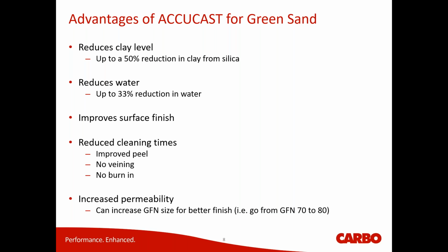So that's just one thing to consider when you're looking at this: you want to really be looking at your permeability numbers for all your foundry processes, what you're running at now, and then look at the ceramic media that's closest to it. That's the most common way to look at it now.